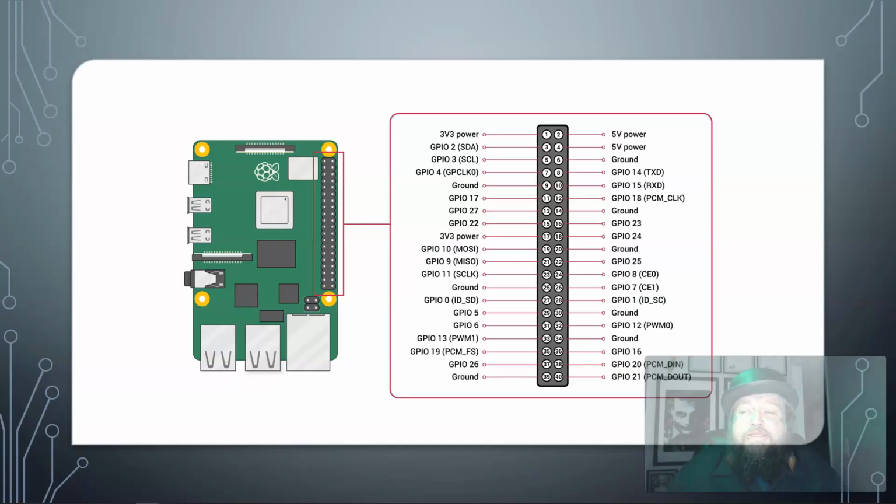So an example is, again, we go back to the Raspberry Pi being a microprocessor. We have the pins and they're numbered, and you orientate the board, you can see it here from where the USB network plugins would be. You'd hold it up and then you get, okay, I can now line these up. That's pin 1, pin 2, pin 3, pin 4, pin 5, pin 6, and so forth down to pin 40. And then you can see the markers for what's what. So, oh, hey, look, this is 3.3 volt. Hey, look, there's 5 volt, ground, so give it power.